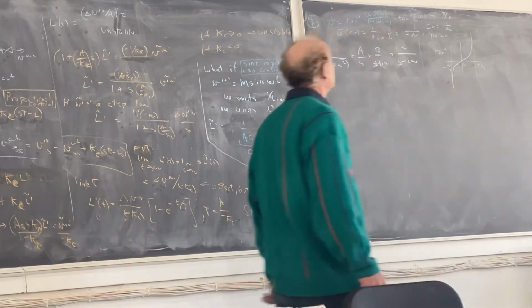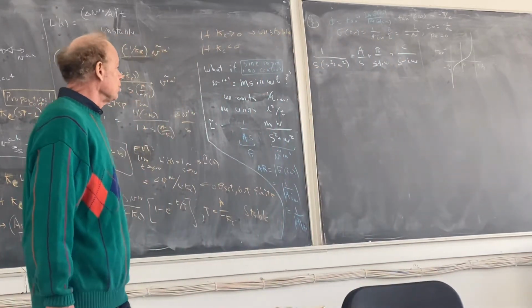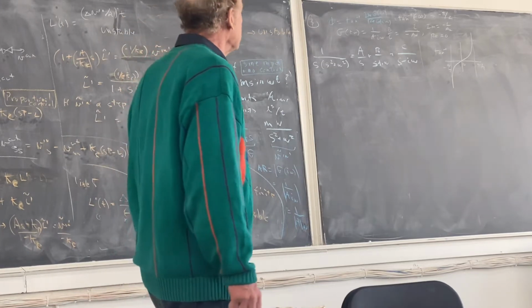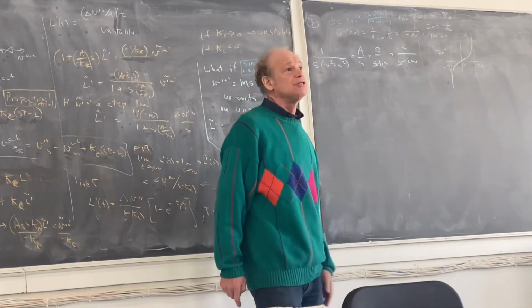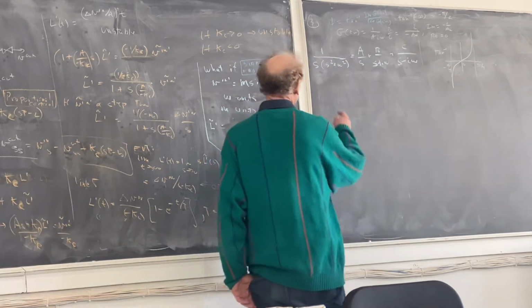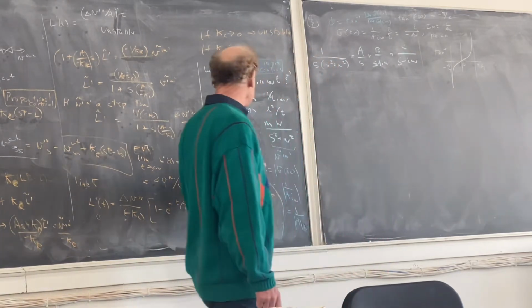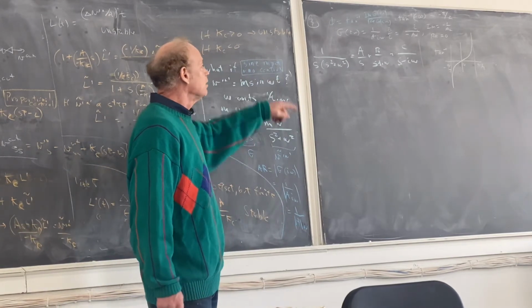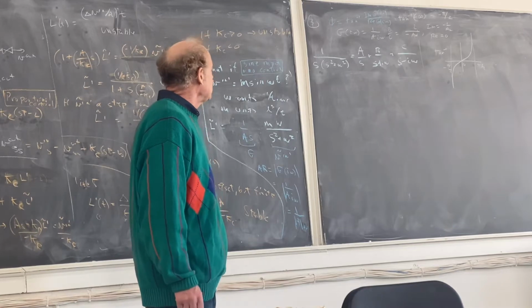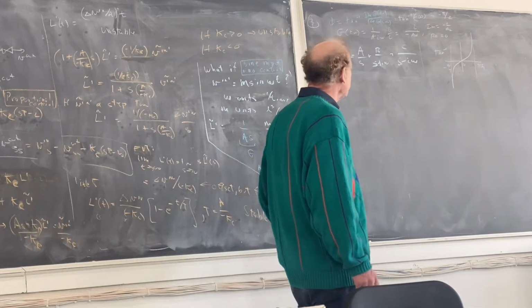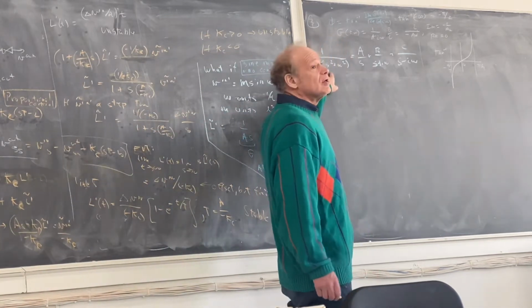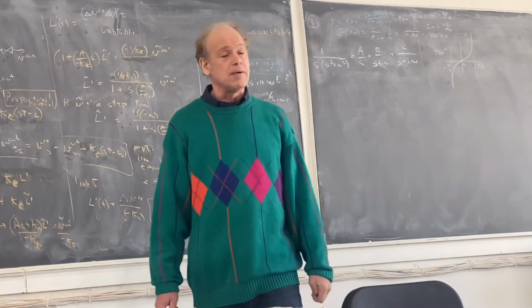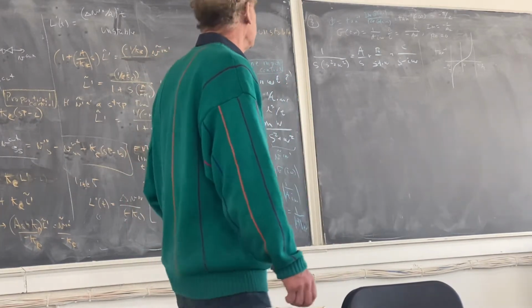So we just determined that directly from what we learned earlier, for the amplitude ratio and for the phase lag, but in this particular case we can also do the inversion directly. So to do the inversion directly, we look at the s dependence here. So we have m omega over a coming along for the ride, and I'm just looking at the s dependence. And because I have a cubic in the denominator, I have 3 roots. So I need to use partial fractions in order to break it up.